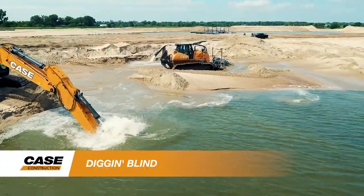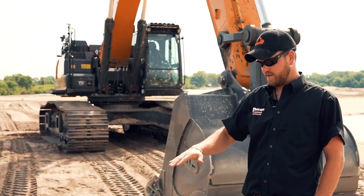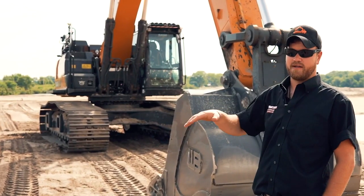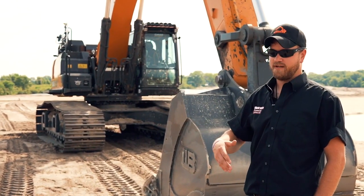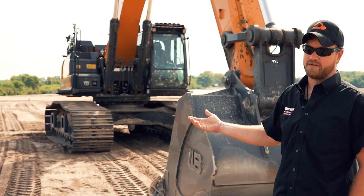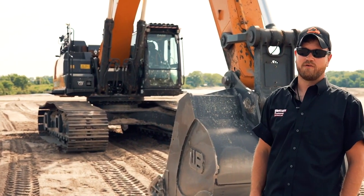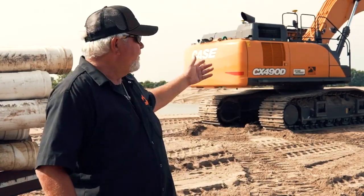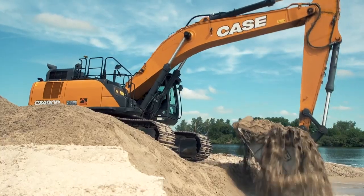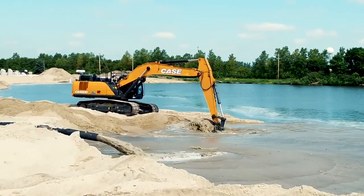We started out with grade control in the 2050 thinking that's all we needed. I could be on a side hill, so I've got to dig up on a grade and load these trucks. Well, if I don't get that to grade, if I under dig it or leave too much, then he's got a heck of a time trying to fill in all that or push how much material to me. If the 2050's over here and you're constantly calling them back, hey, strike me off grade, strike me off grade. And if we're digging on the side, all these shorelines now, I can dig all to grade with this machine and be perfect, spot on.